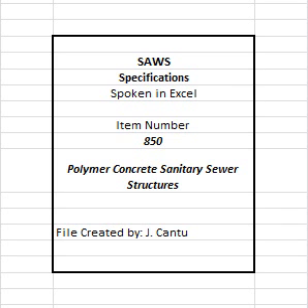D2584. C. Resin selection shall be suitable for applications in the corrosive conditions to which the polymer concrete manhole structures will be exposed. D. Resin additives, such as curing agents, pigments, dyes, fillers and thixotropic agents, when used, shall not be detrimental to the structure. 10. Provide resilient connectors conforming to requirements of ASTM C923 or other options as available. A. All connectors are to be watertight. B. Install approved resilient connectors at each pipe entering and exiting structures in accordance with manufacturer's instructions.